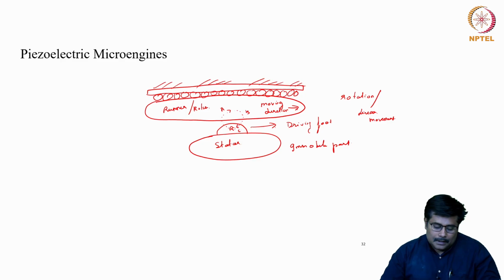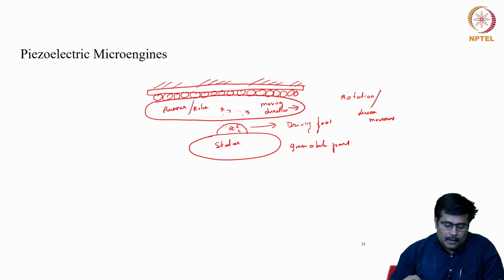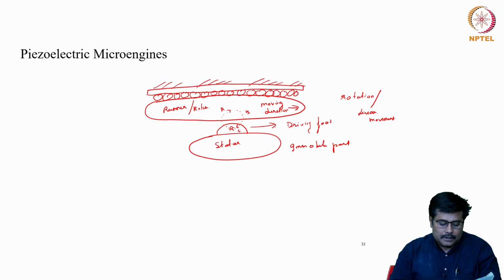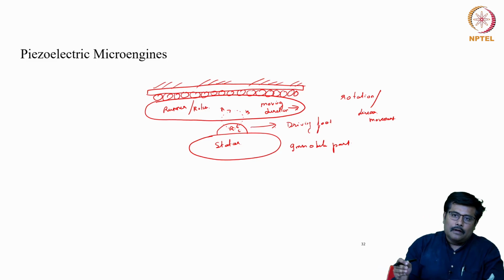It is something like this: the pushing element of the circular motion moves the runner with a friction force, while the pressing element shifts the force that is normal between the driving foot and the runner on a periodic basis. The pushing and pressing elements are parallel and perpendicular to the runner's travelling trajectory respectively.